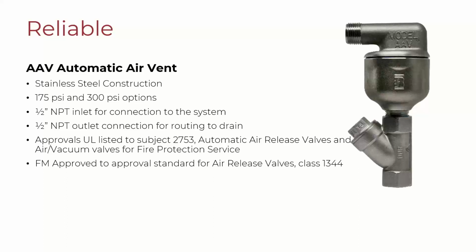One of the major shoulds is to make sure that anytime you are installing an air vent, you absolutely have to make sure the air release mechanism is installed vertically. It can't be off the sidewall of the pipe. It can't be installed at an angle because things do not float well sideways. So it's very important that you make sure the contractor has done their job rightly and the engineer has designed rightly, so that the air vents are installed in a vertical orientation.